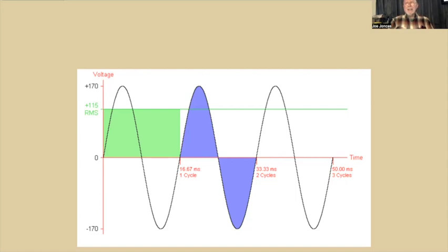If we talk into the microphone on a radio and look on the screen of an oscilloscope, we can see the peaks. So we take that peak voltage, multiply it times 0.707. Then whatever voltage we get, we square that and divide it by the resistance, 50 if we're using a 50 ohm load. So that's E squared over R.